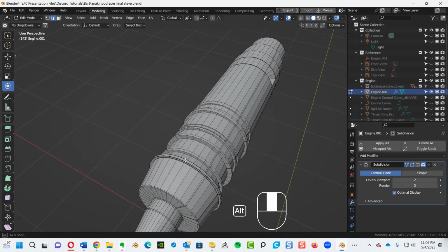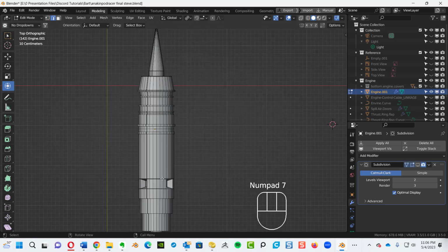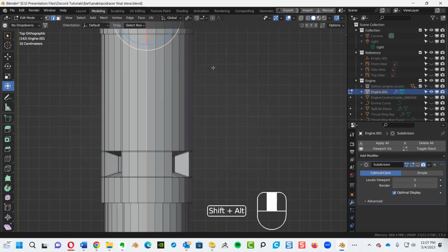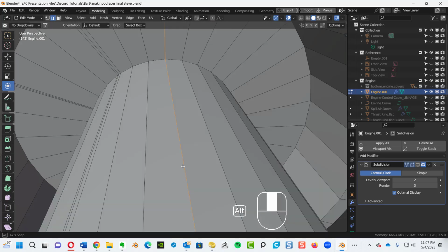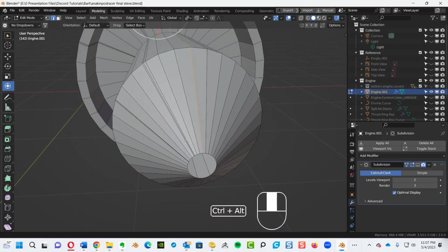All right, so to create my UV edge, I'm going to the top view. Okay, and I think all I need is one edge on this one. So I'm going to press the number 2 key on the keyboard to go to edge editing mode. Double click this edge here, and it's going to be an edge loop all the way around the top. All I need is one along the top.